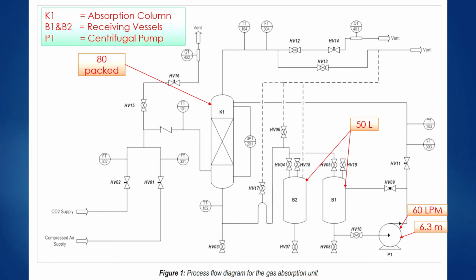For the general startup procedure, ensure all valves are closed except ventilation valve HV13, fully open. Drain any stagnant liquid above the sampling valve HV03. Third, open the valve on the compressed air and CO2 supply line. Set the air supply pressure to 0.2 MPa and the CO2 supply pressure to 2.0 MPa by turning the regulator knob clockwise. Turn on the main switch.